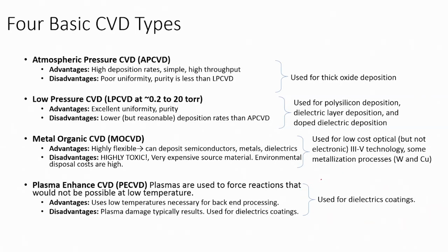What is PECVD? The advantage is low temperature, you see. We can deposit silicon dioxide or silicon nitride at a relatively low temperature, from 100 degree centigrade to 400 degree centigrade, that plasma enhanced chemical vapor deposition uses, and that is why it is used in MEMS applications, MEMS based sensor fabrication, which we have just seen, where we can grow silicon dioxide with PECVD.